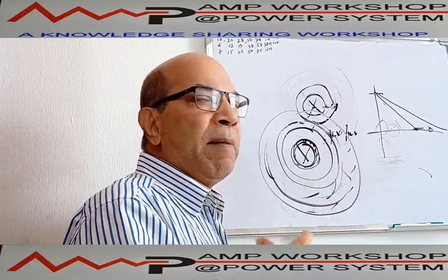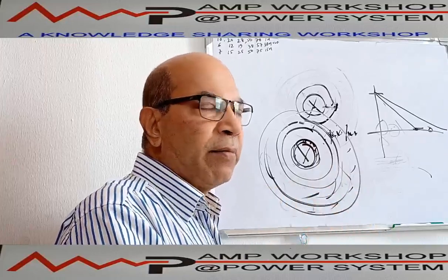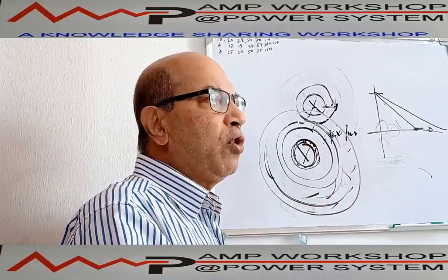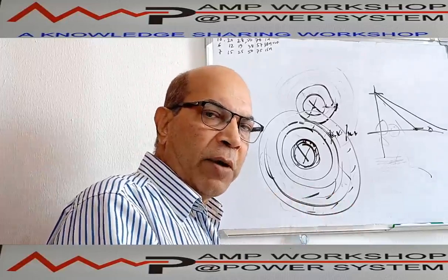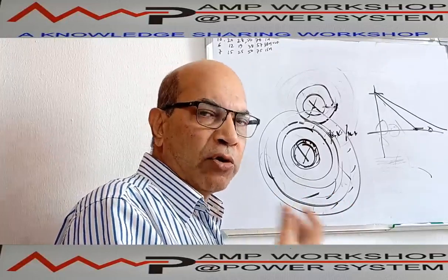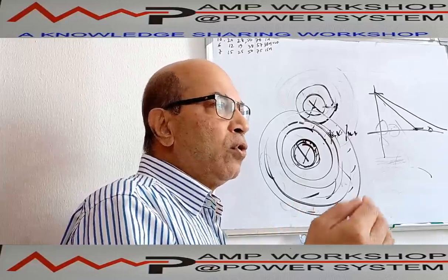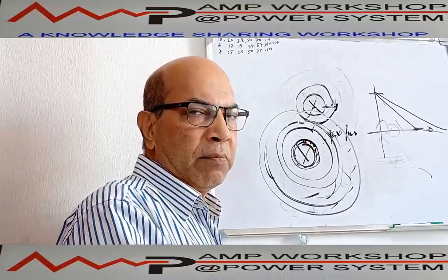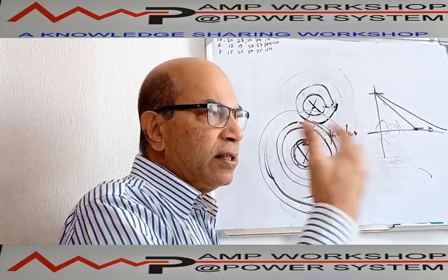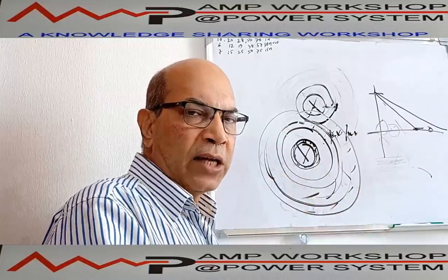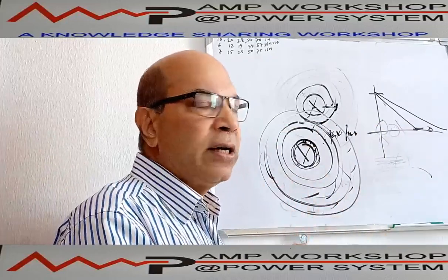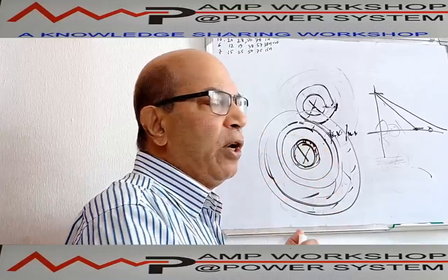Then we have to put the mechanical protection, that is mechanical armor. Over the armor, what do we have to put? We have to put another plastic cover, that is PVC, called the outer sheath, which will prevent any external liquid or external gas from entering the cable, so that the armor will not get damaged. So these are the major components of the cable.